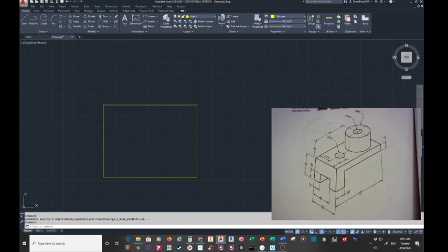But if you were to look at this from this side, this surface under here where this little L shape is, it intersects in this corner, and that line for that corner goes across underneath. Well, from here it would be a hidden line. Well, if you look at it from the other end, from the right hand side in this case, it's actually going to be a solid line because you're showing the bottom surface edge and the top edge here.